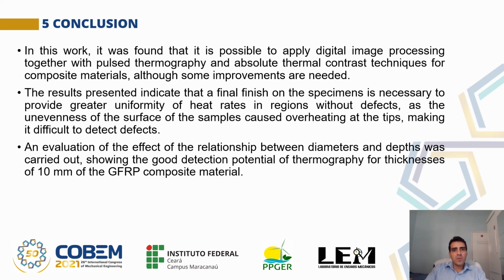Conclusion. In this work, it was found that it is possible to apply digital image processing together with pulsed thermography and absolute thermal contrast techniques for composite materials, although some improvements are needed. The results presented indicate that a final finish on the samples is necessary to provide greater uniformity of heat rates in regions without defects, as the unevenness of the surface of the samples caused overheating, making it difficult to detect defects.